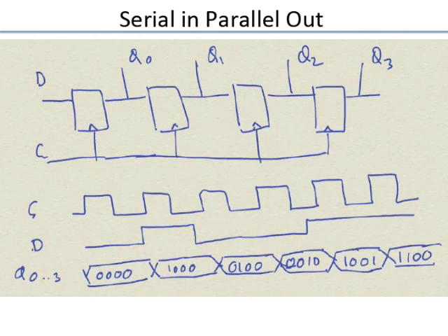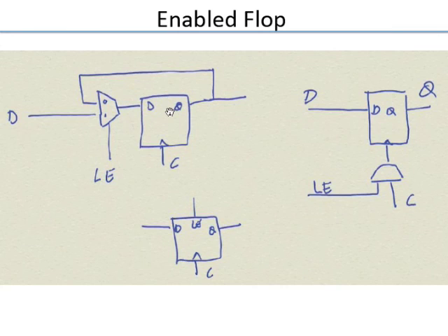For example, whenever you are toggling, you have activity, which means power consumption goes up. All the toggling is exposed, because if you have a combinational logic which is seeing that, everything is just toggling unnecessarily, and it's a waste because you really don't care about these intermediate patterns. You are just going from one to the other. So to prevent that, well, what you have to do is you have to have one more level of registers.